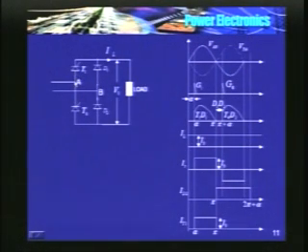So, the potential of A does not appear at the cathode of D3. So, D3 continues to conduct. I repeat, D3 continues to conduct, whereas in the lower half we have an uncontrolled device D2, a common anode configuration. So, immediately D2 starts conducting. The moment D2 starts conducting, a negative line voltage appears across T4, and T4 turns off.